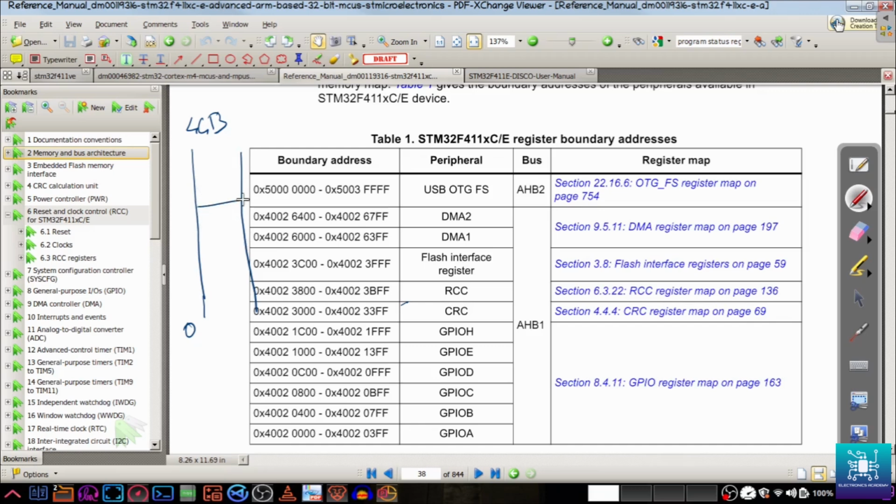So you have code memory. We will have a look at that as well, the memory map. You have code memory, you have data memory, and so on. You have flash, you have RAM, and all your peripheral control registers are also a part of that same memory. So everything is accessible using addresses in the same address space, and not all 4 GB is used. Parts of the 4 GB are used as the processor vendor wishes, but the basic boundaries have to be respected.